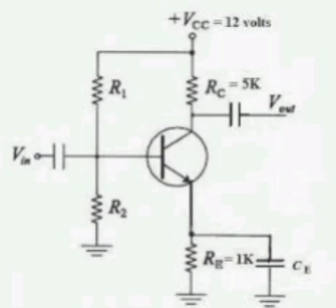The parameters of the amplifier shown in the figure below are RC1 equal 4 kilo ohms, RE equal 2 kilo ohms, RC2 equal 5 kilo ohms, RF equal 4 kilo ohms, and RS equal 200 ohms. The DC bias currents of the transistor are IC1 equal to 0.5 milliamperes, IC2 equal to 1 milliampere. Transistor parameters hFE1 equal to hFE2 equal to 150. Use the techniques of feedback analysis to calculate the input resistance RIF, the output resistance ROF, and closed loop transresistance gain AF. Assume VT equal to 25 millivolts.